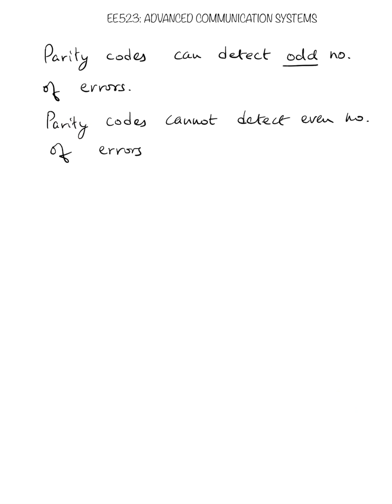So 0, 1, 1 is our data. When we transmit this 0, 1, 1 and we receive 0, 1, 1, the receiver checks for even parity. That means the receiver would check if the number of ones in this is even or not. In this case, the number of ones is even. There are 2 ones, so it accepts it as a valid code word.